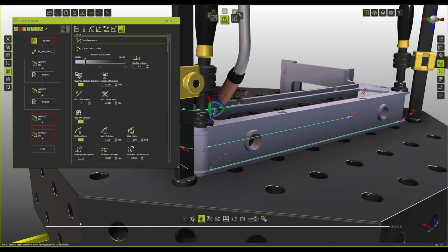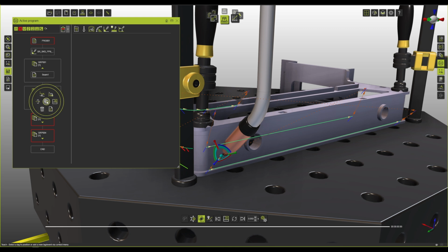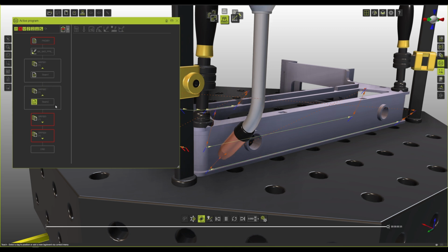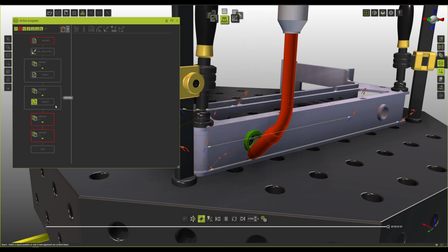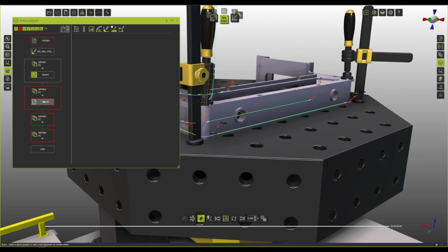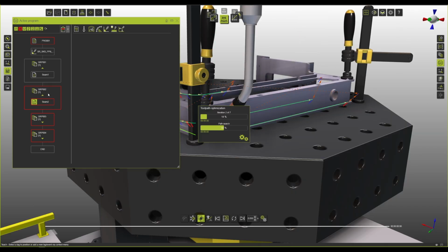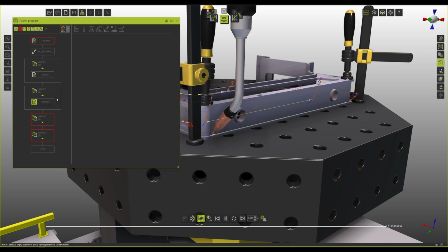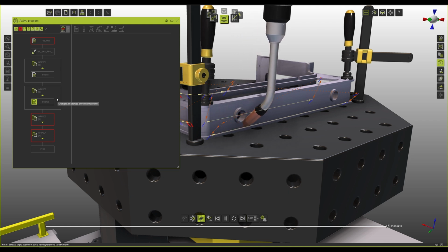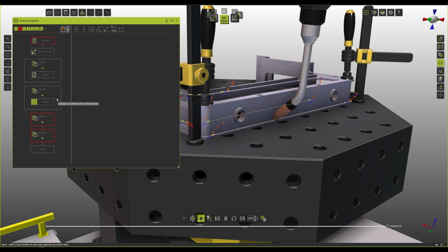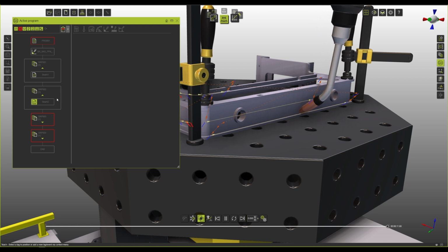The last part of the settings comes with this motion check. So this motion check does an iterative search to see if the optimization that has been created is valid not only for the toolpath elements, but also okay for the rest of the toolpath. So that means if you go in sections that are long, it does not only modify the beginning and the end, but it checks something in between. So in the cases where you have a collision or you have some problems in the middle, it will also try to solve it. This works hand in hand with the insert process points.